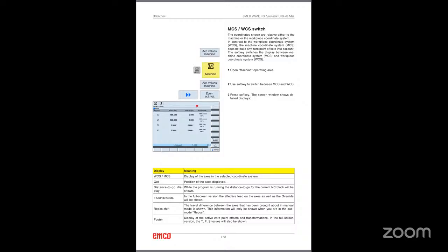So program level means suppose you have a very large CNC program. That means you have a main program, a subprogram, another subprogram, consisting of different levels. The machine will show which level you are in right now. This is what is called a program level. For example, you have a main program, then it calls a subprogram, and again it calls a subprogram. That means the machine is at subprogram level. The program level window will show all this. This is to debug large production programs.